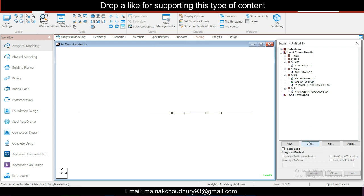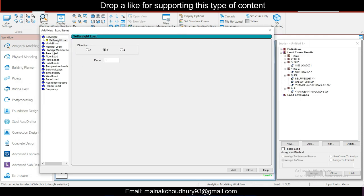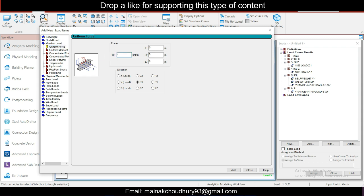Click on add parapet wall load, let's say will be member load -3, add, and again we can add here a load for the staircase portion. It will also be 4.5 meter, a little less I assume. So let's give 10 for the staircase and lift portions. Okay, so this will add and then close.